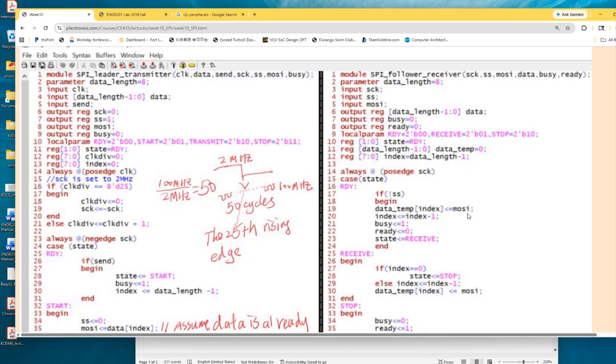But you only have one SPI module on your microcontroller. You're not expecting 10 SPI modules on the microcontroller. It's going to take up so many pin resources, right? There's sometimes one, sometimes two SPI modules. So for one microcontroller, you only have, for example, one SPI module, then there will be only one MOSI, one MISO, one SCK, and one SS. That's it. But you need 20 sensors hooked up to one brain.